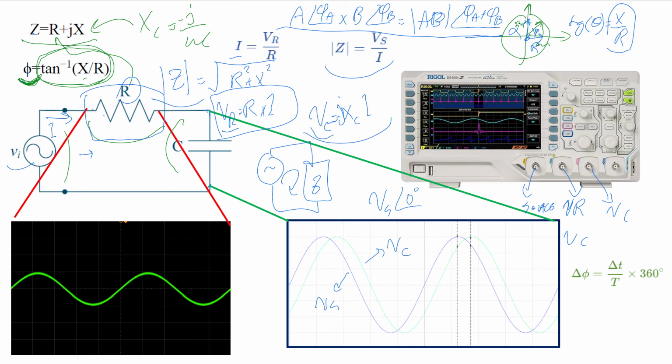You don't have direct access to the phase difference, but your function is in time difference. And we know that the phase difference in phasor translates to the time difference in the time domain. So you can measure the shift of the time between peak to peak, or 0 to 0, they are going to be the same, and have your delta t, the time shift between the values.